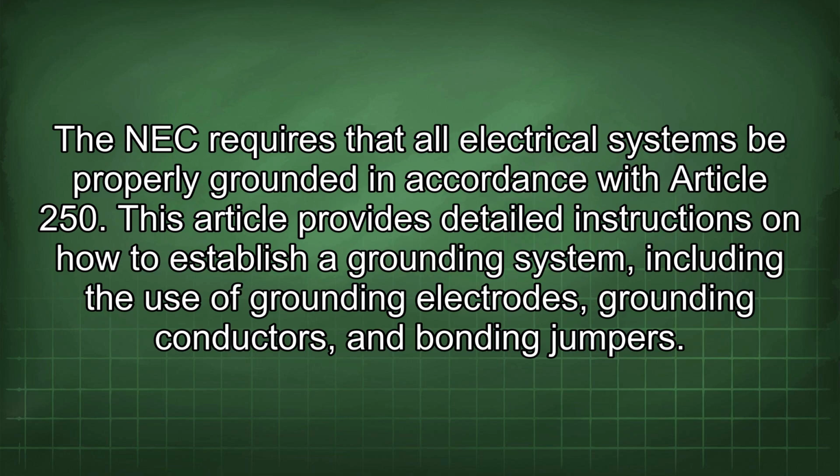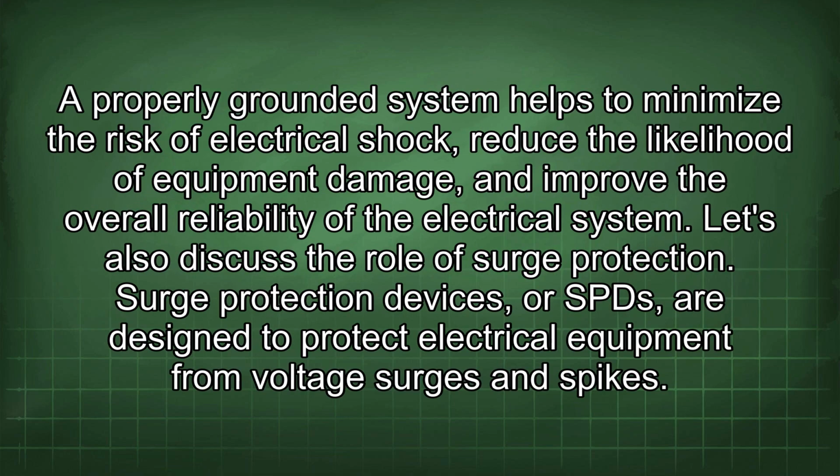and bonding jumpers. A properly grounded system helps to minimize the risk of electrical shock, reduce the likelihood of equipment damage, and improve the overall reliability of the electrical system. Let's also discuss the role of surge protection.